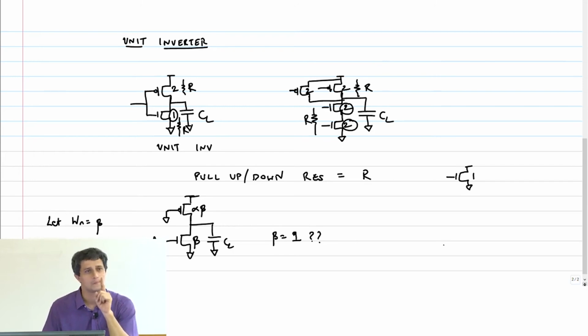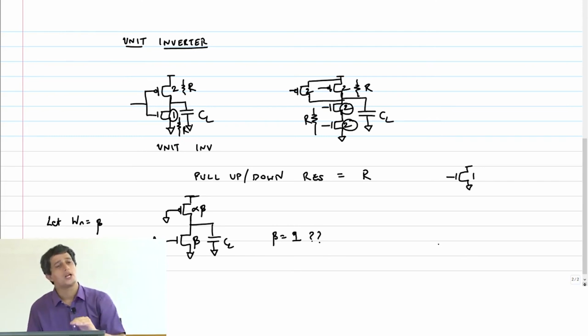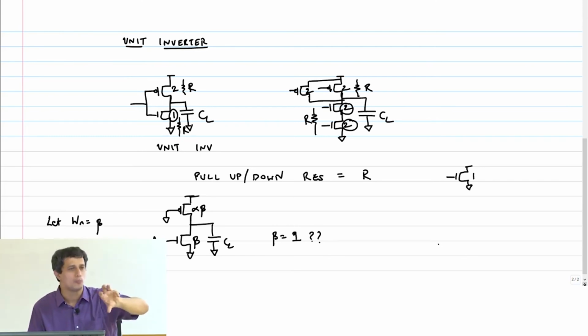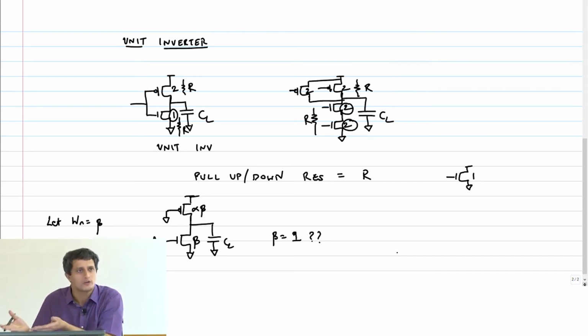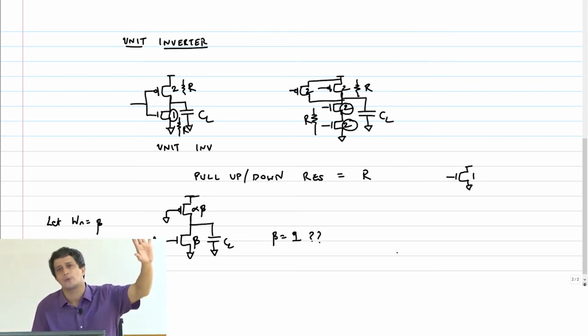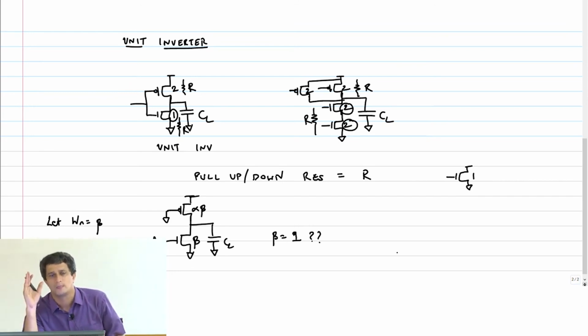The catch here is, unfortunately, my PMOS transistor is also conducting when the output is being pulled low. Inherently we are saying, I am going to pull down the logic very quickly, so we are sacrificing the pull-up speed because we have to lower the PMOS size. We have no other go so that the low logic works correctly. So I have already compromised the pull-up speed. That's already been done, so I'm not going to worry about the pull-up speed. What about the pull-down speed? That's what I'm going to worry about.